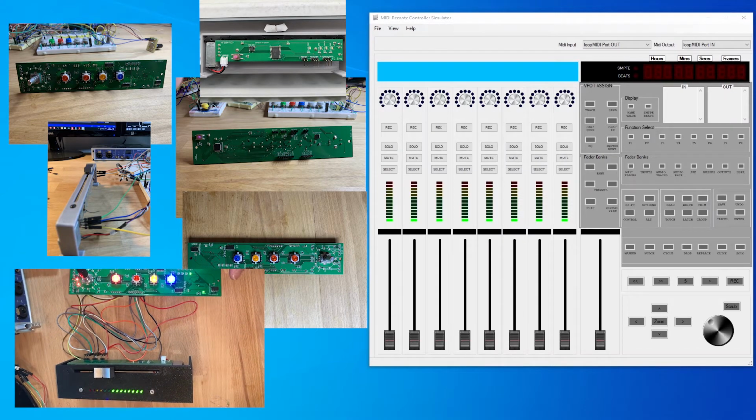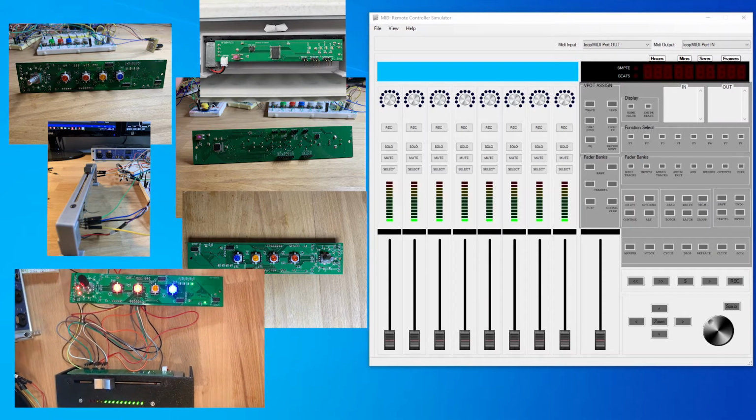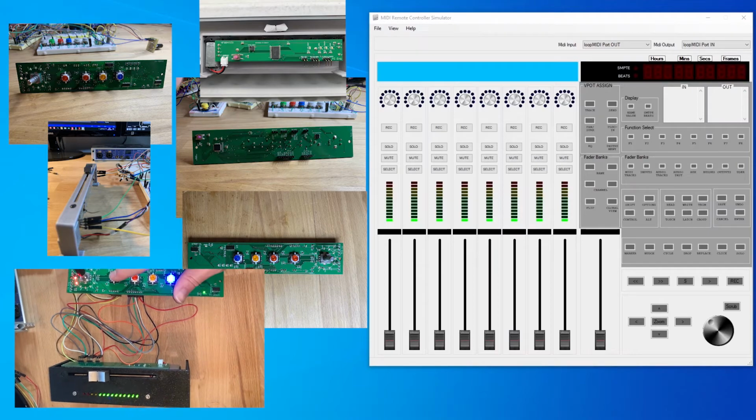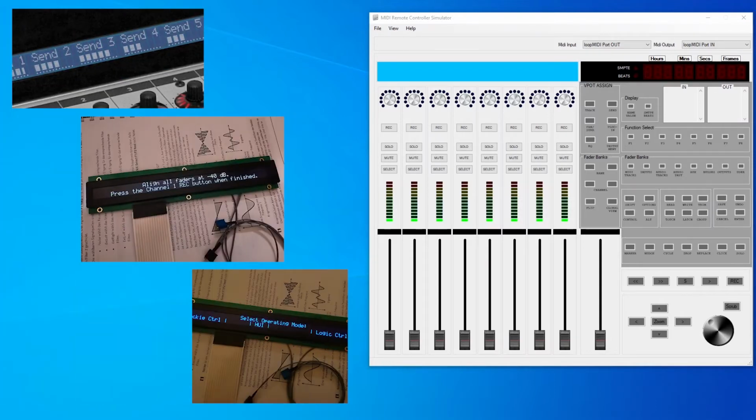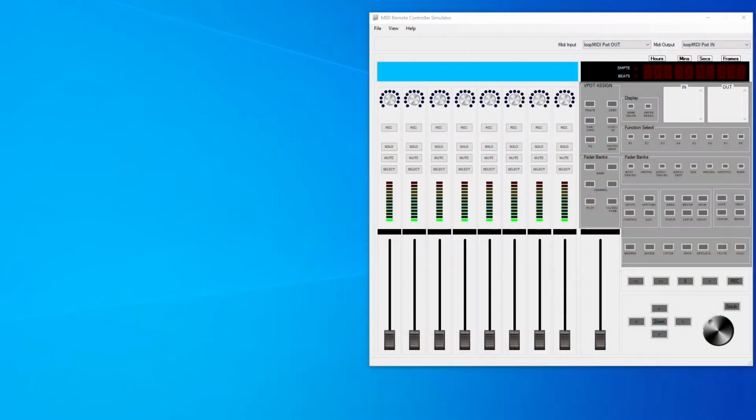There is additional scattered information around, but nothing really clear, up-to-date and consistent. At first I started prototyping some parts of my control surface by trial and error, but at a given moment I came across some showstoppers, for instance the main LCD display. The Mackie surface uses a 2x56 character LCD display, which is almost impossible to find on the market. Understanding how the interaction between the surface and the DAW worked in this respect was far from evident. Also, developing the V-pot encoders and the 7-segment display was not so clear, and so I finally found myself stuck in the mud. Until I started developing this software simulation.